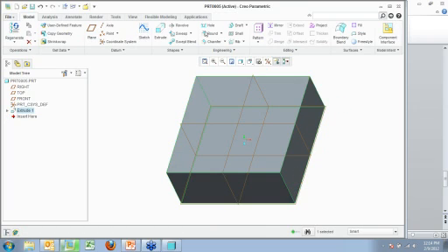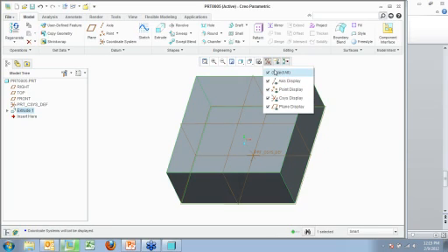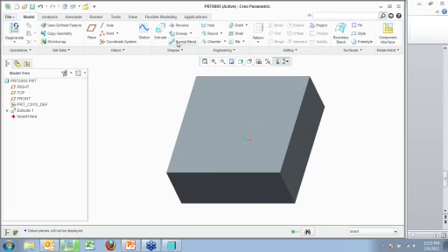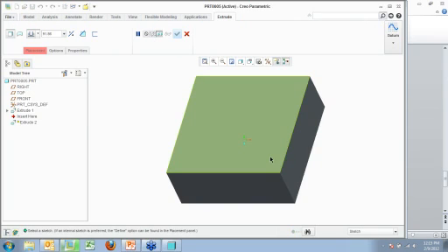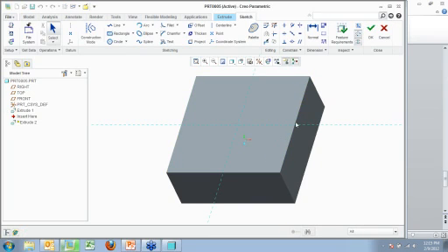So now, here's one of my favorite features. We'll turn our planes off here. I'm going to go in and make another extrusion right on top. Select this here. So I want it to snap to this corner here. I don't have to select the references. I can just go in, grab my rectangle. This time I'll do a standard corner rectangle.